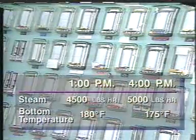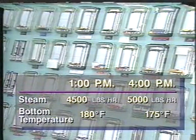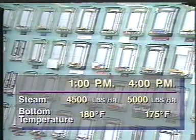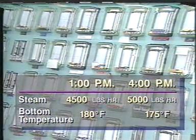If the total picture of the operating conditions seems unreasonable, you should question whether the data shows the actual state of tower conditions. Suppose instrument readings tell you that the flow of steam to the reboiler has increased and that the temperature at the bottom of the column has decreased. Other tower variables remain the same. Does this data fit together? If you answered no, you are correct.